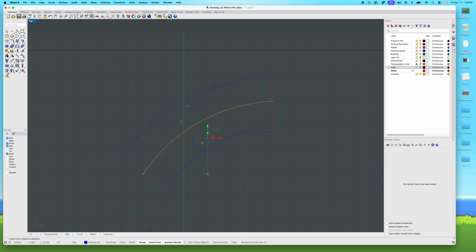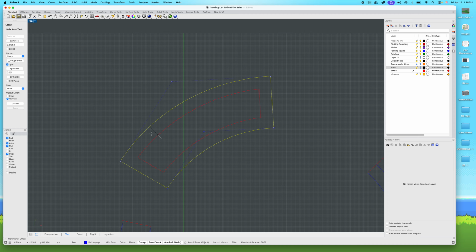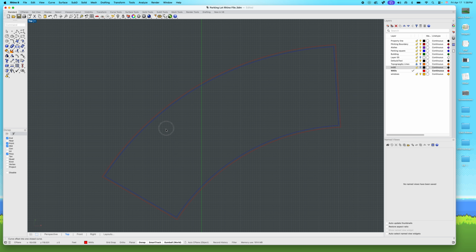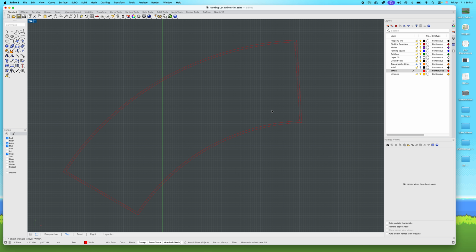So, well, let's turn it into something, right? But I don't necessarily want to offset that all over again. So in my case, I'm just going to join them. How thick is a wall? Well, anywhere from a foot to 6 inches. So in my case, maybe I offset it and I type literally a foot, so 12 inches, enter, and voila, right? I start to have actually some of my wall systems. Right click and change object layer. But as you can see, really nothing to it, right?